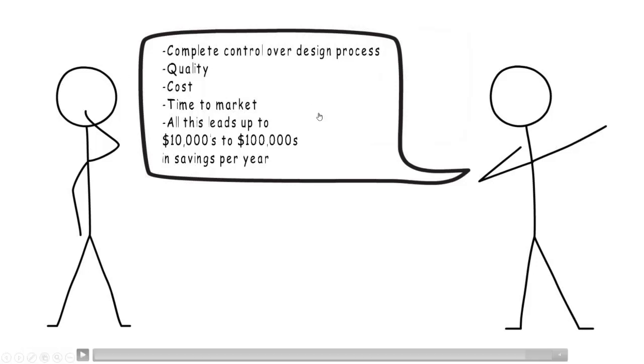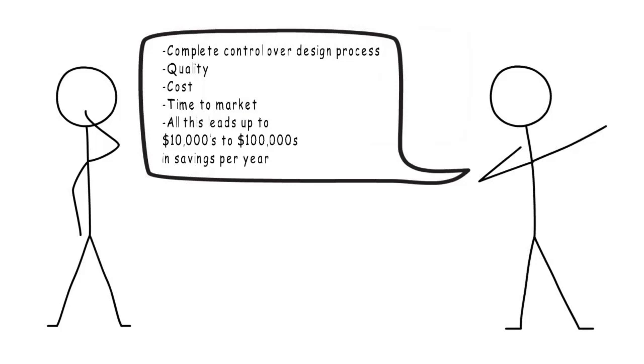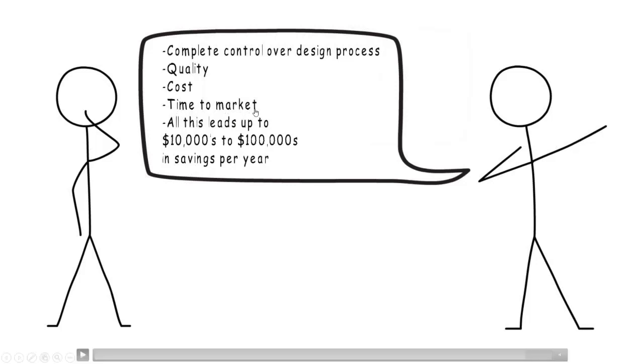You're not having to do as many design spins, possibly, if you have issues related to DFM, DFA in the past. Time to market, you're definitely going to be able to hit those marks when you say this is the schedule, because your fabricator and assembly contract manufacturers are not going to hold you up with time delays in doing verification for you, or if they find problems, you having to go back and fix it.